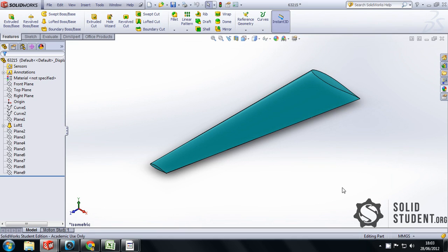There are a couple of ways of modelling these curves in Solidworks. You can use the equation-driven curve function, that I'll do another video on, or you can use the insert curve function, which imports a file with a set of coordinates for the curve you're trying to create. In this example, I'll be importing a set of coordinates for creating an aircraft wing.